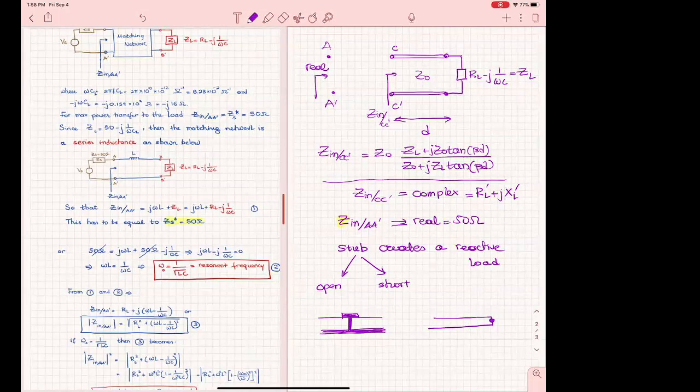If you can avoid it, you always avoid punching through the wafer, unless you absolutely have to. There are cases where you do, but if you don't, in the microstrip I'd rather do an open stub. And a microstrip in 3 dimensions is going to look like this, for example.